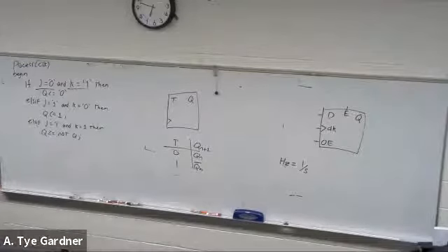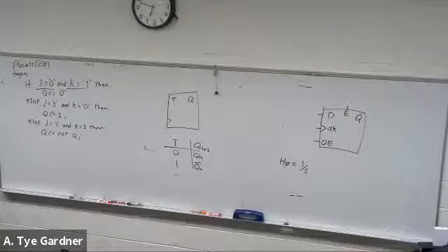So all T is doing in this case is saying flip or don't flip, just flip-flop. This is like the fundamental flip-flop. Either do it or don't do it. Unsurprisingly, you can very easily build a T flip-flop out of a JK flip-flop. I might actually save that for a homework though, because it's kind of fun and simple.